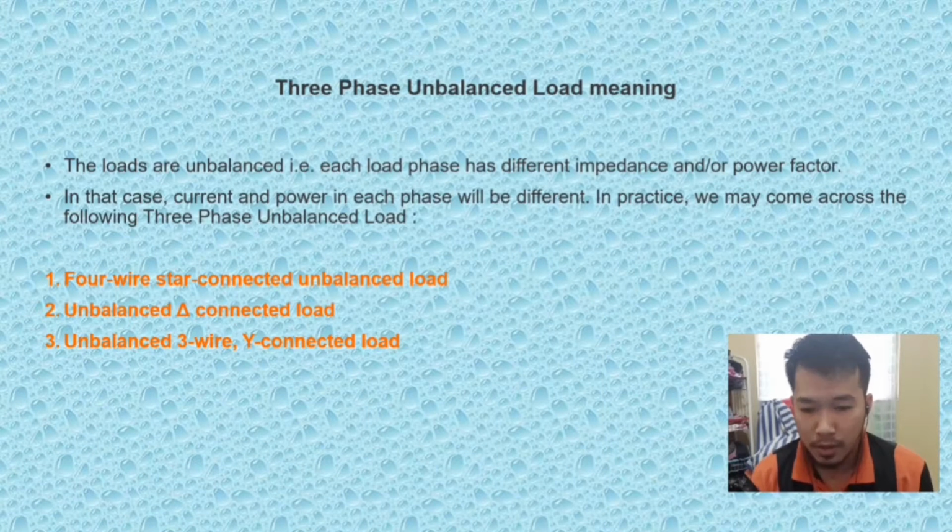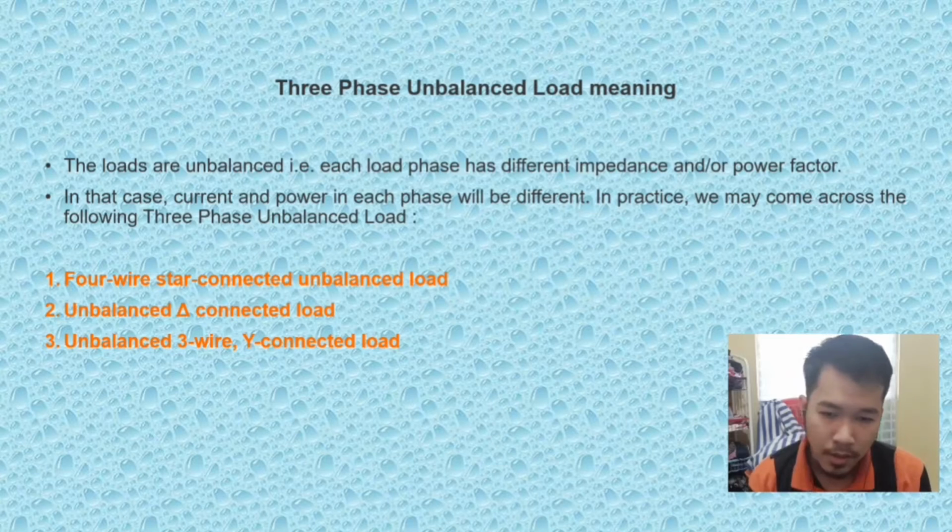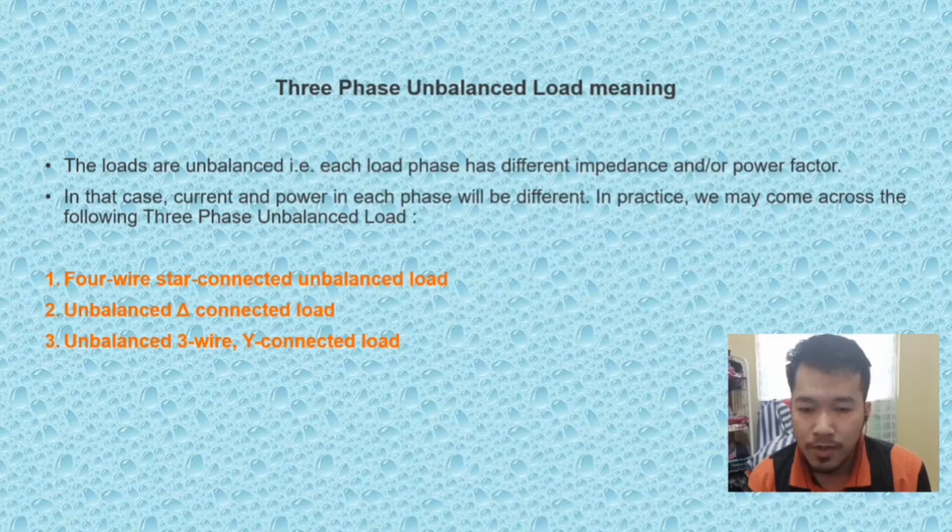My name is Afiq bin Naim and I will continue the explanation from Faris about the technical briefing from this assignment task, and I will explain about the three-phase unbalanced load meaning. The loads are unbalanced when each load phase has different impedance or power factor. In that case, current and power in each phase will be different.